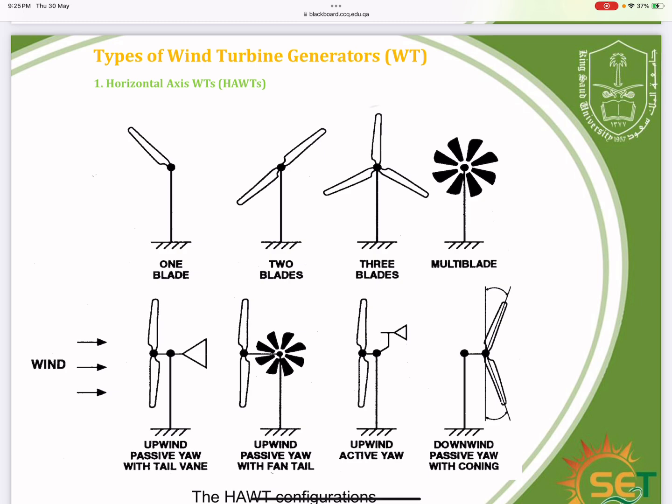But in my opinion, for most modern wind energy applications, 3 blade turbines are the best option due to their balance of efficiency, stability and noise levels. So I would go with 3 blades.